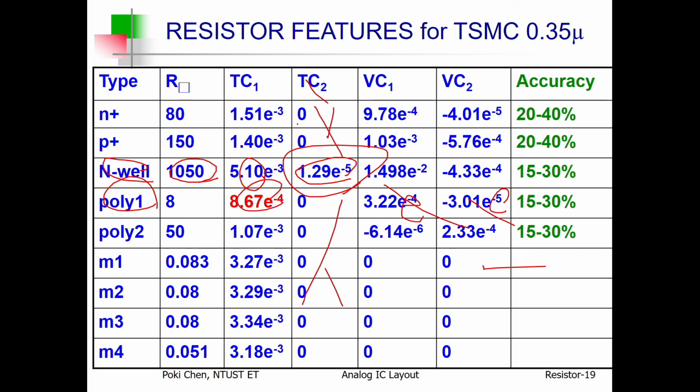Only for some cases, where you only need a large enough resistor and you don't need to pay attention to the characteristics of the resistor, then you can apply NWell. Only if the resistance is large, that's it, you can use NWell. For many of the other applications, I told you already, don't touch.